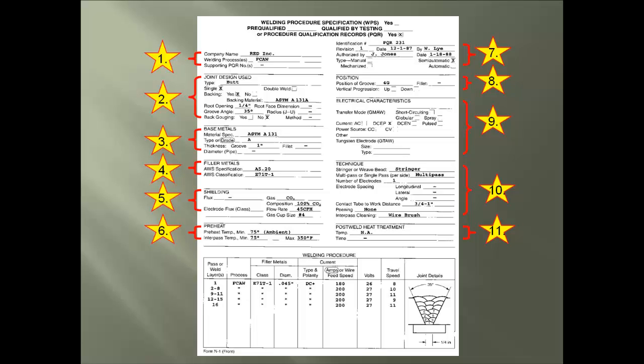Now let's take a look at a chart that will spell out each individual pass for the weld joint, and this chart is called the welding procedure. To start, here is what the weld joint in this PQR will actually look like. And we have a groove weld. Does it match the line items for positions above? Remember, the G stands for groove welds, but you will be surprised how often this simple step is incorrect, which makes this form not in compliance for proceeding with any production welding.